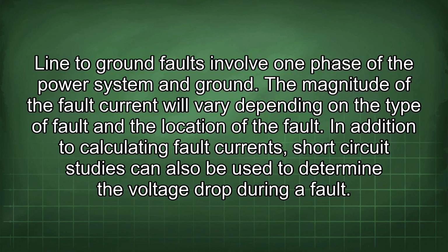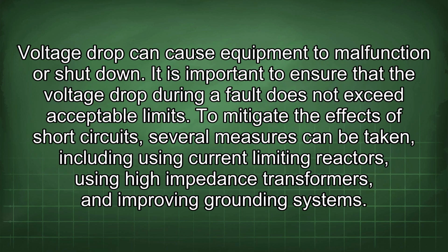In addition to calculating fault currents, short circuit studies can also be used to determine the voltage drop during a fault. Voltage drop can cause equipment to malfunction or shut down. It is important to ensure that the voltage drop during a fault does not exceed acceptable limits.